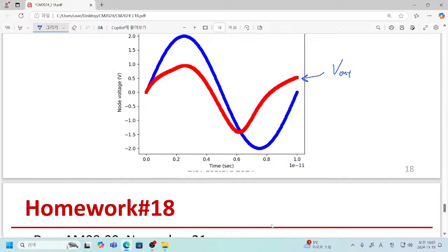However, when you consider a logic device, the maximum frequency we can use for this logic device is actually determined by its frequency behavior. So, for example, if we have a certain logic technology whose capacitive components are quite huge, then we cannot make rapidly reacting inverters. Then it means that we cannot use it for high frequency operation or high clock speed.